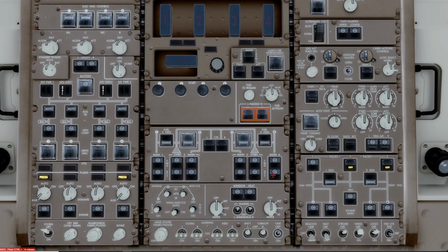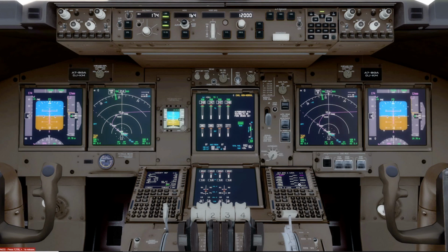And then we do the before taxi flow, followed by the before taxi checklist. So the FO would come up here and turn the APU off. Demand pumps 1 to auto, 4 to auto. Engine anti-ice if required. It's not required today. We don't have visible moisture. We're not at 10 Celsius or below. We come over, turn the packs on. So then we come down and select flaps. We're using 10 today, so we'll go flap 10.